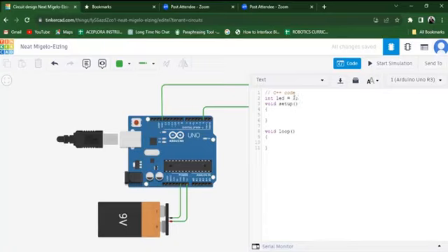You use characters when the variable is assigned to letters, and so on and so forth. So we have different types of data type, right? I'll drop a note on that in the group so you can understand more about data type. But for the purpose of this practical, we are using int for now. Since we are assigning the variables to numbers, we use integer. So int LED is equal to 2.